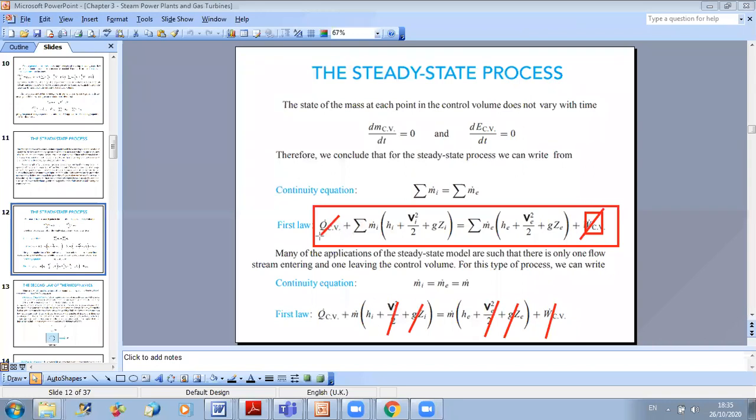You can take the water separately and the refrigerant separately, but it will add to your calculation, because you will need two equations to end up with your result. So the easiest way to get rid of the heat exchange between the two is to take the whole system of the two fluids. So you will have two inlets, two outlets. And this is what we did here.